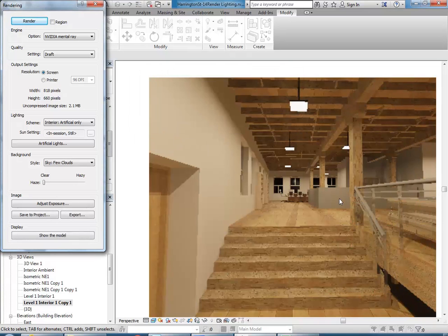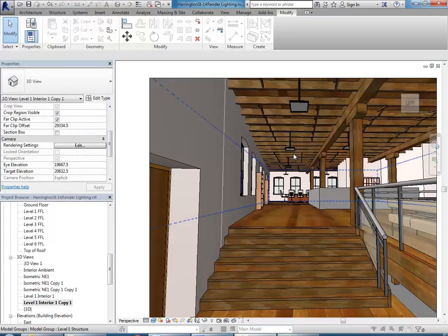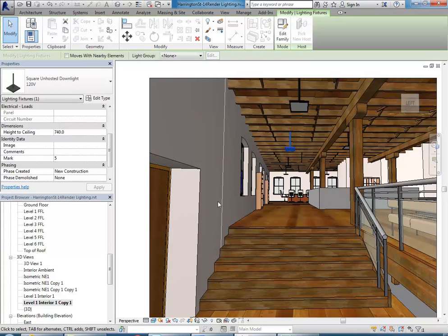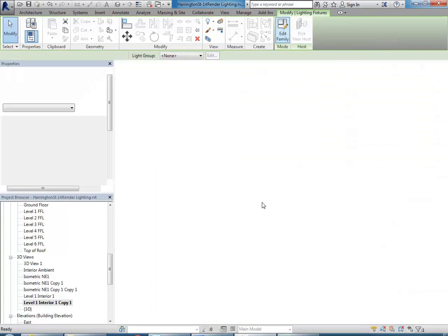So, yep, it's a little bit officey, but I don't mind it for the sort of ancillary spaces, that light source. But now I want to have one that's a little bit different for the reception. So I sort of roughed out this reception area, and now I want to have some directional lights in that space. So we're going to use this light as a starting point and modify it to put those in. So I'm just going to go to Edit Family,